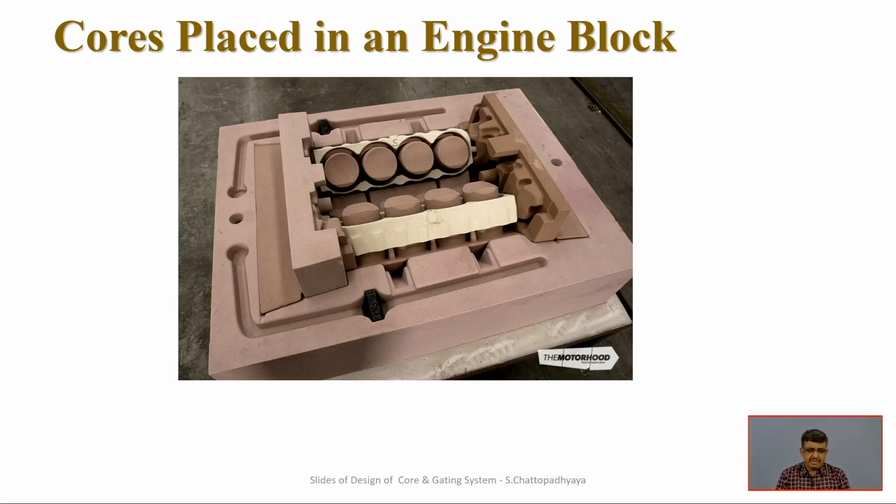much difficulty. But the placement, the alignment, and the concentricity of the placements are very crucial, because otherwise there will be an alignment and other kinds of error, and if appropriate metal is not provided after machining, that will be a defective casting. So the concentric placement of those cores inside those hollow structures of the mold is very critical.